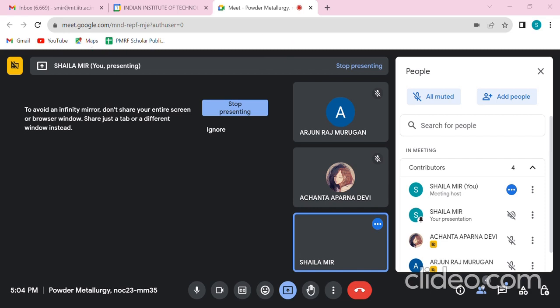For annihilation of these pores, there are different methods of filling them. One of them is mass transport, where the material from some other portion will occupy this pore or vacancy, and as a result the material will be densified. So during the sintering process, mass transport occurs with the pores. That is a right option, because that will help in achieving a higher density. The pores are involved in the densification process also.